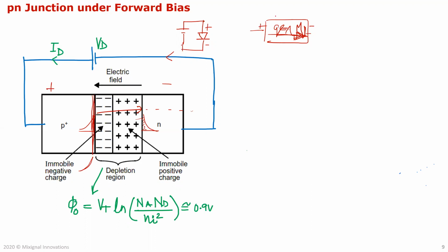Actually for an electron it will be moving in this direction. That's called drift. And diffusion is in a semiconductor: if I just bombard a bunch of electrons, like a spike of electrons into this material, and let's say I have some potential across it, then this will actually diffuse, just from recombination. That's called the diffusion current.